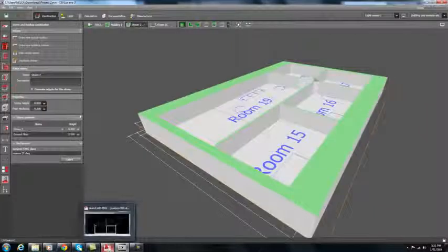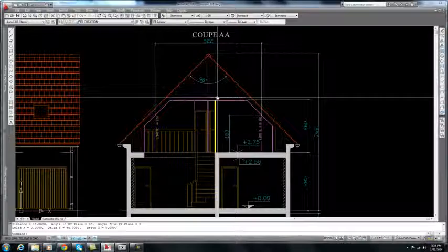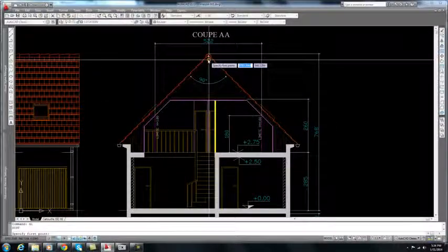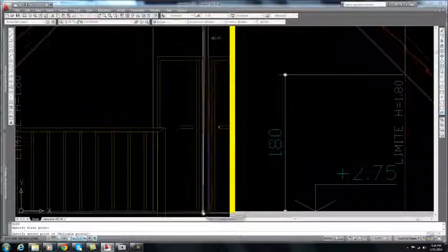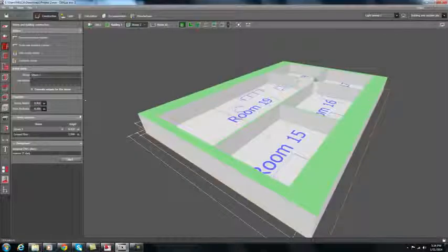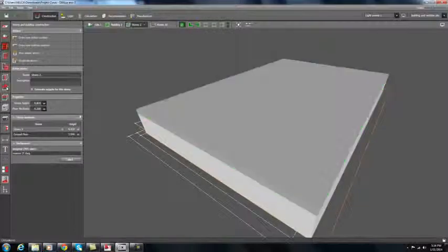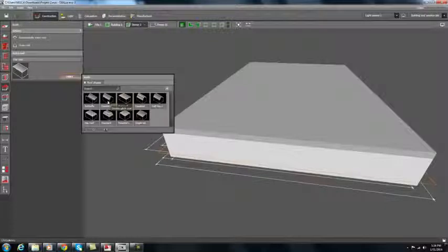Alright, so let's go back to the drawing CAD file again and check the height of the roof. Go to this inner part of the roof and go to the finished floor line, and you will see it's 4.5. Let's go back here and go to this roof tab, and then in the roof tab you will select a roof that is similar to ours.